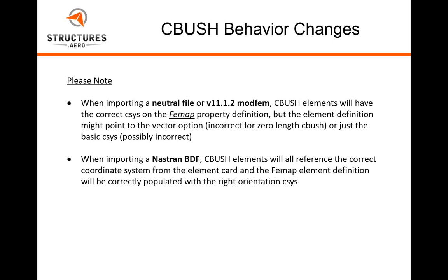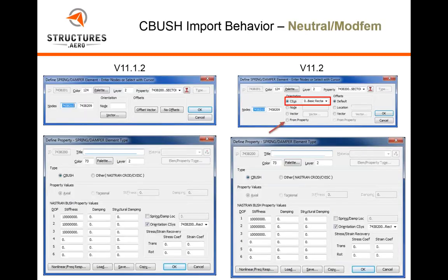But I should also note that if you import from a Nastran bulk data file, all the CBush elements will correctly reference the right coordinate system that was on the element card, and the Femap element definition dialog window will be correctly populated with the right orientation coordinate system.